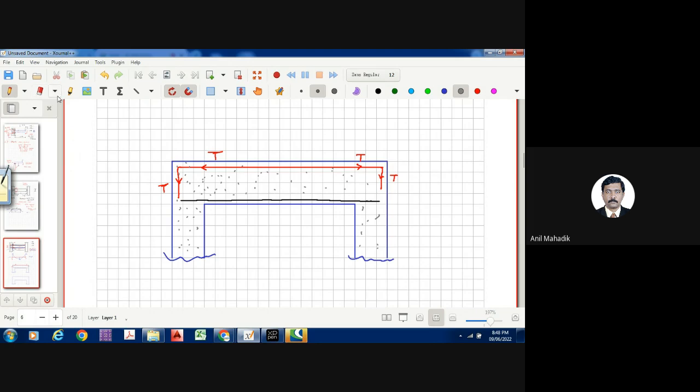For the time being, let me delete this. I think so. This one. But okay, let's consider this line is a line of compression in the concrete. Okay, so there is a compression possible here. ये compression possible है due to concrete and even reinforcement is also there in RCC beams. So which will take the compression? Let's say there is a reinforcement, it will take the compression, and the concrete will also take the compression. So this T is there and this C is there.